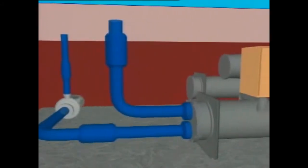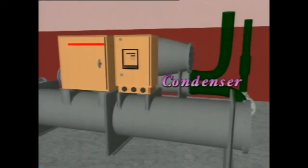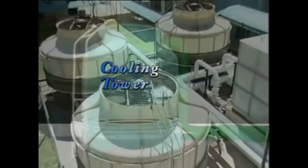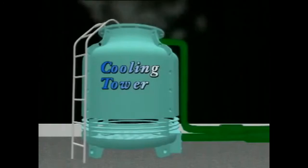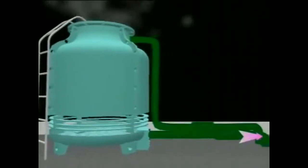The heat transferred to the refrigerant will be passed to the condenser water circulating through the condenser. After absorbing heat from the refrigerant, the condenser water temperature will be raised from about 29 degrees Celsius to 34 degrees Celsius. The condenser water is then pumped to the cooling tower, which is located outdoors. The heat absorbed by the condenser water is rejected to the outside air. The 29 degrees Celsius condenser water collects in the sump of the cooling tower. It then flows back to the condenser of the chiller to again absorb heat, and the cycle repeats.